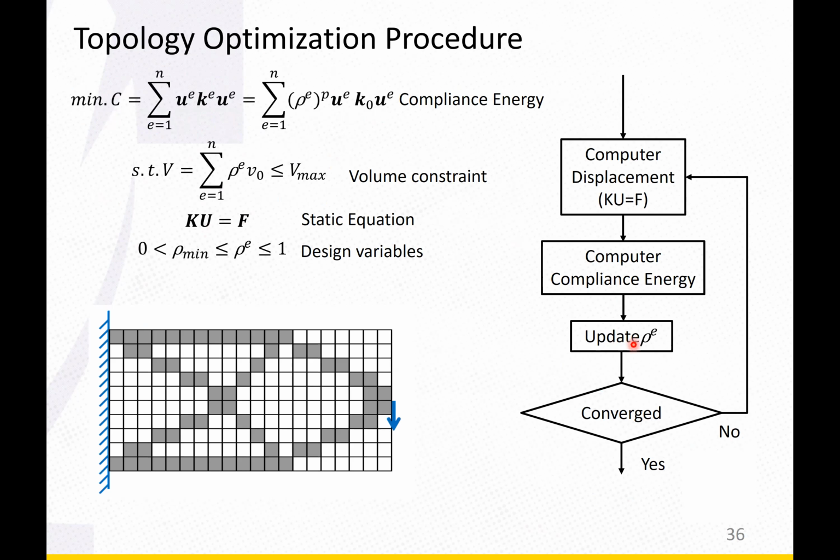And here gives you a typical routine for topology optimization. And actually it is an iteration. So first of all, you just specify the rho value to be 1 at all of the grids in your basic design domain. And then you just do the iteration step by step and update the rho, which is the density at each grid. That is why when you check the video, you can see a transition from the original base domain to the final pattern.